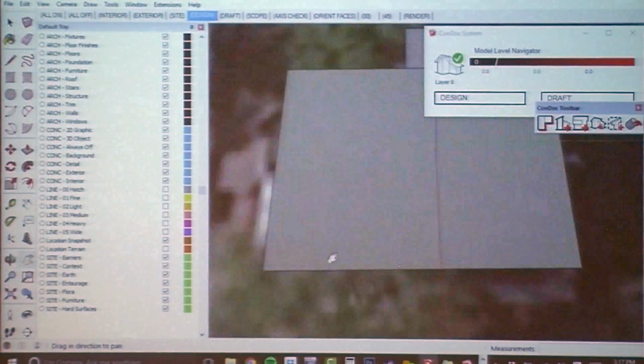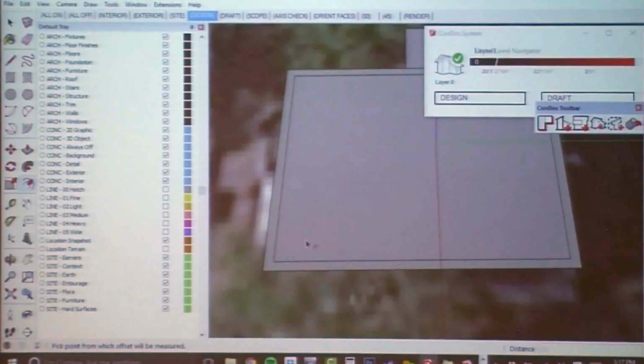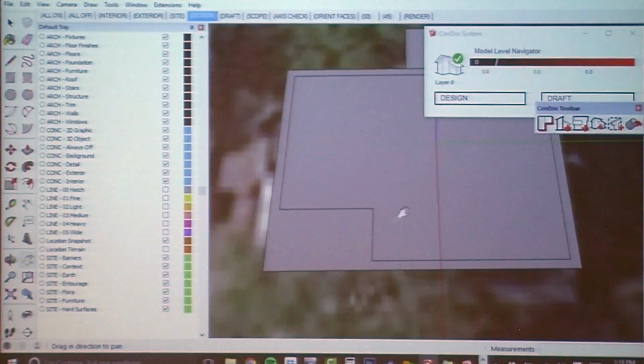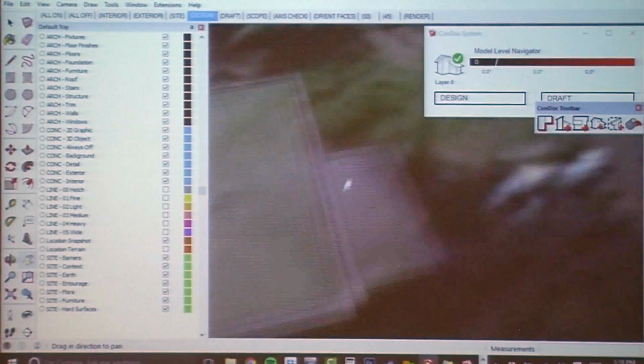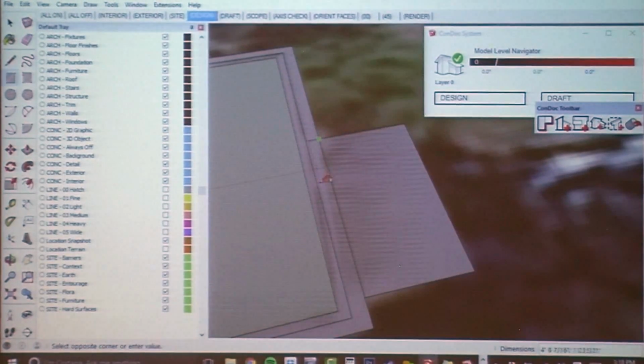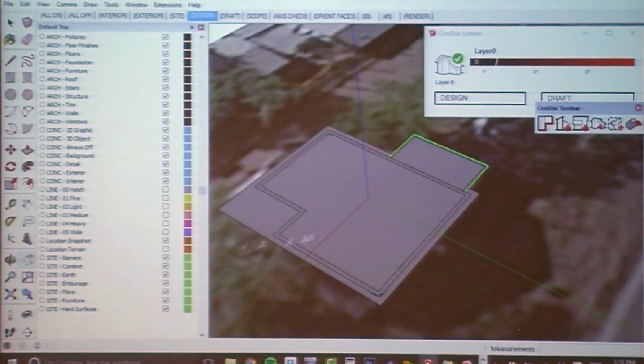So what I'm going to do is just kind of make an assumption on my offset of 12 inches for the roof. And then I'm going to draw a rectangle down here at 10 feet by 6 feet for that front porch. Trim out that geometry and then offset by 8 inches. Next, on this back wall, I'll fill in these lines here. And then we're going to offset this by, say, 5 inches, just to make some line work to work with in Layout.